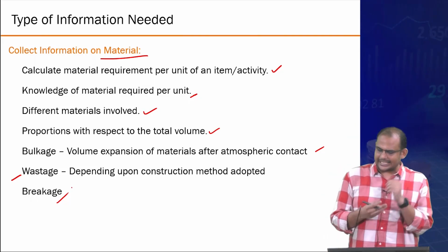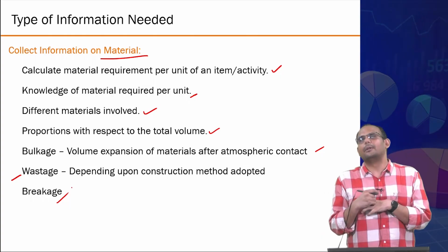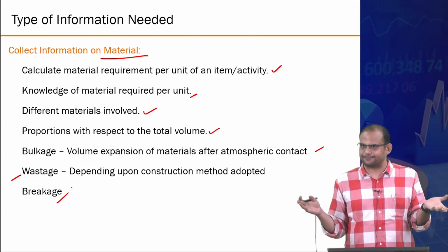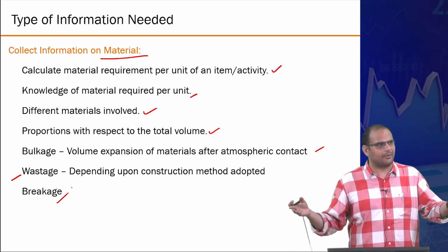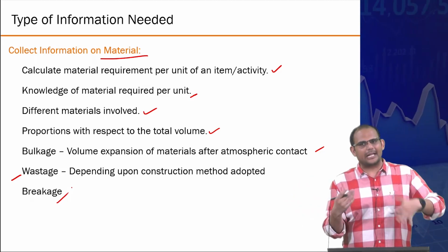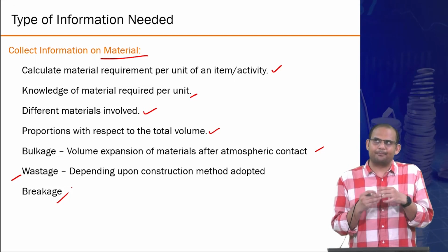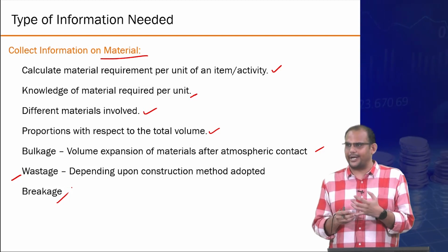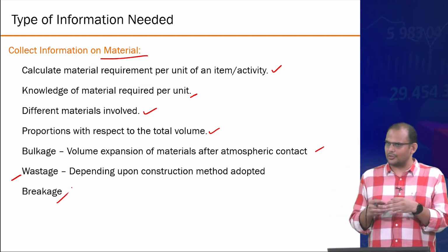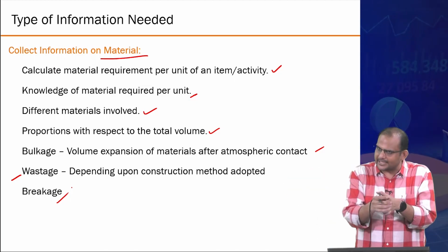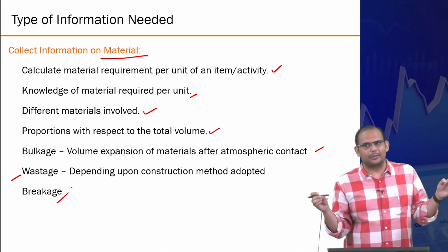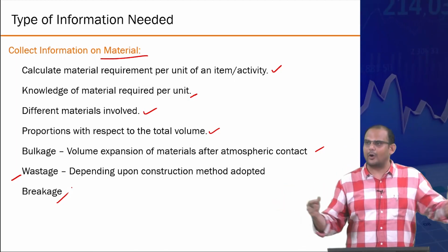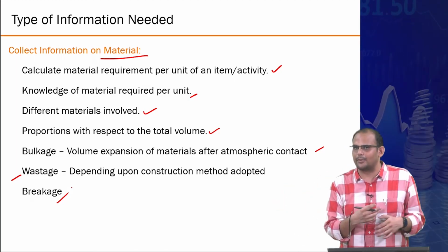In terms of wastages, I think a good example would be the rebars, right? The rebars come with a pre-specified size from the manufacturer. So depending upon how your rebar schedule is able to accommodate, you might end up with so many small pieces, or you could have optimized your rebar calculation so that you are having whole bars or longer bars compared to many small bars.